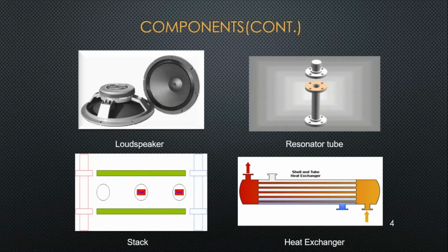The stack is the most important component of the thermoacoustic refrigerator. It is the heart of the thermoacoustic refrigerator. It is basically a geometry that can locally form temperature zones and locally store heat. It is the main reason why the temperature gradient can be formed in a thermoacoustic refrigerator. And then we require a heat exchanger so that from the hot side the heat escapes continuously, and from the cool side we can draw cooling, like an evaporator in the vapor compression cycle refrigerator.